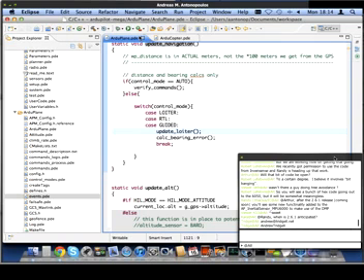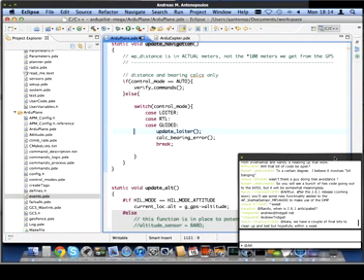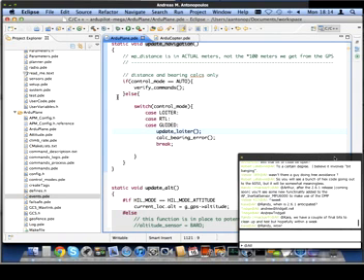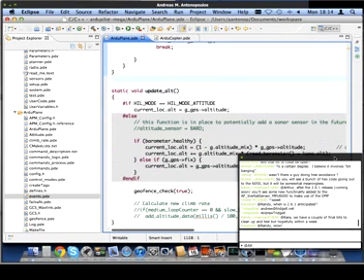One of the areas that I don't think is particularly well developed is the automatic transition between sonar altitude and barometric altitude. Plus, I don't think we've got particularly good code for calibrating your sonar. It's quite important to know the calibration between the reading that you get from the sonar and the actual altitude, and we need some better mechanisms for calibrating that to ensure that we have an accurate altitude in centimeters.